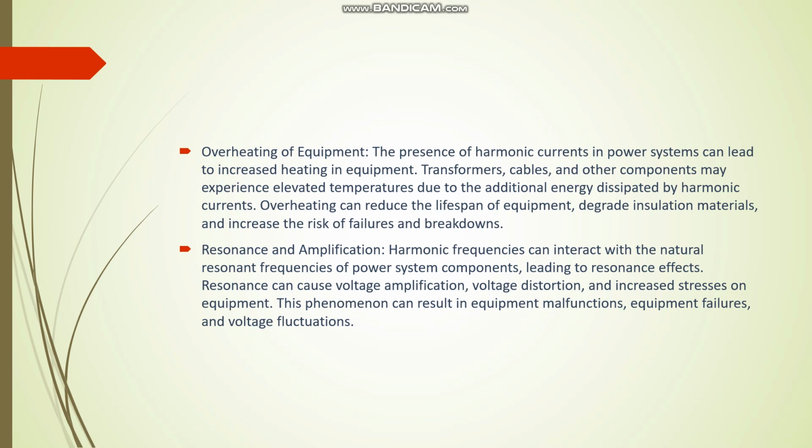Resonance and amplification. Harmonic frequencies can interact with the natural resonant frequencies of power system components, leading to resonance effects. Resonance can cause voltage amplification, voltage distortion, and increased stresses on equipment. This phenomenon can result in equipment malfunctions, equipment failures, and voltage fluctuations.